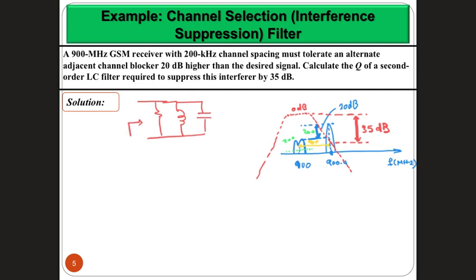And remember, I'm not going to do the derivation here, but remember from your circuits that such a filter will have an impedance Z which is a function of frequency. And if we want to put it in the form of the transfer function, we will put it as a function of S, which is S equal to j omega in this case. And it's equal to RLS divided by RLC S squared plus L S plus R. So this is the impedance in general as a function of frequency.